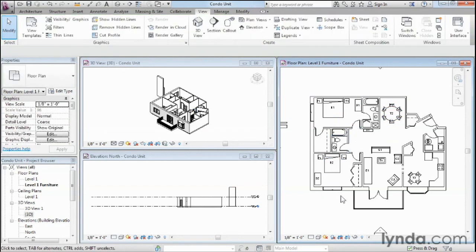If you want to select more than one object, the easiest way that you can do that is to use either a window or a crossing selection. Now, both of these are very similar to the counterparts in AutoCAD. The difference is the way that you execute the windows and crossings. So in AutoCAD, you would click and then click to create a window, but you'll notice here in Revit, it doesn't do anything when I do that. In Revit, you click and drag to get a window selection. In all other ways, it behaves exactly the same way, though.